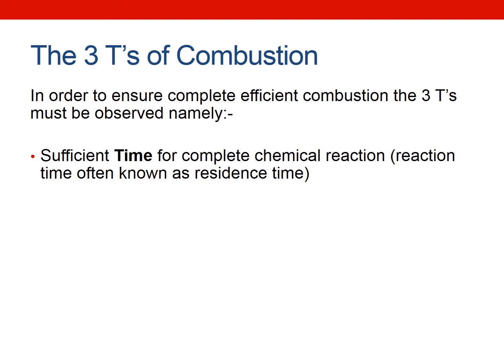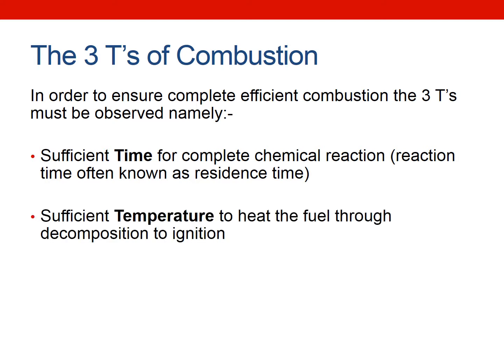This is sometimes known as residence time. To put this in the context of an engine, if you've got a very high RPM, the time for combustion is finite. It needs to occur. So you want to be careful that you have time for that combustion to occur before you're discharging the reactants, as in the exhaust stroke. So that's important. The second one is temperature.